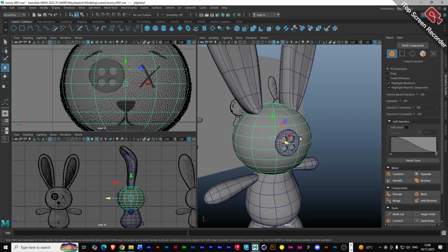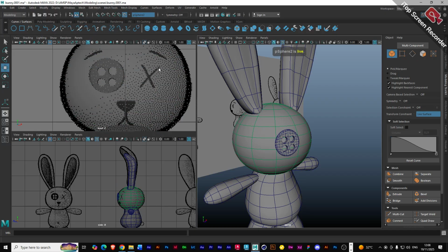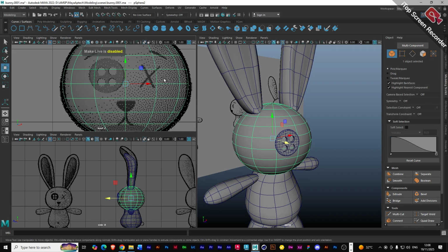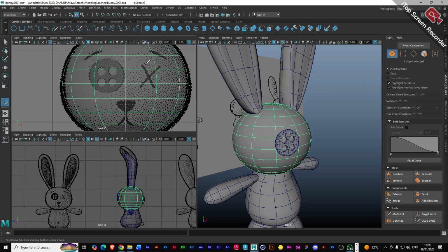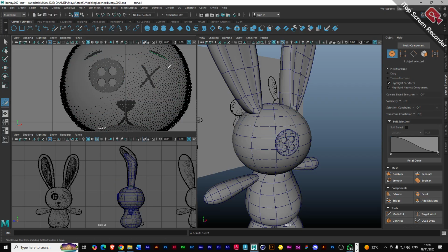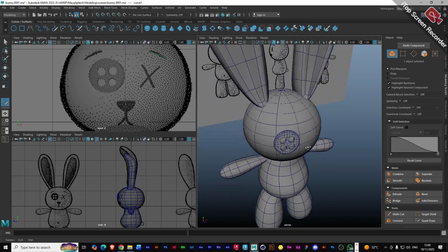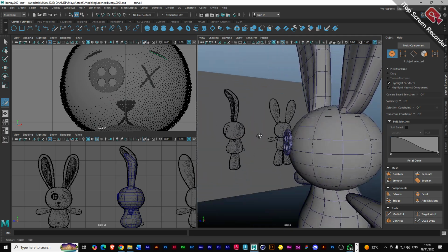So if I'm going to use curves for this guy, I might make this surface live. There is an option Maya has that allows you to draw along the surface of an object. Right now, if I take my curves and just draw a line like this, it's not going to be attached to the surface of my object.